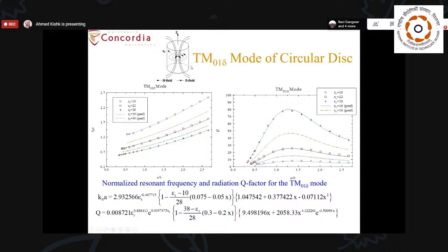Because the height in a cavity is always a multiple of half wavelengths when it is bounded by conductor from the top and the bottom. But here it is an open surface by dielectric, so this height can never be exactly lambda over 2. That's why they use this δ, and the society never agreed on a unique definition for this.